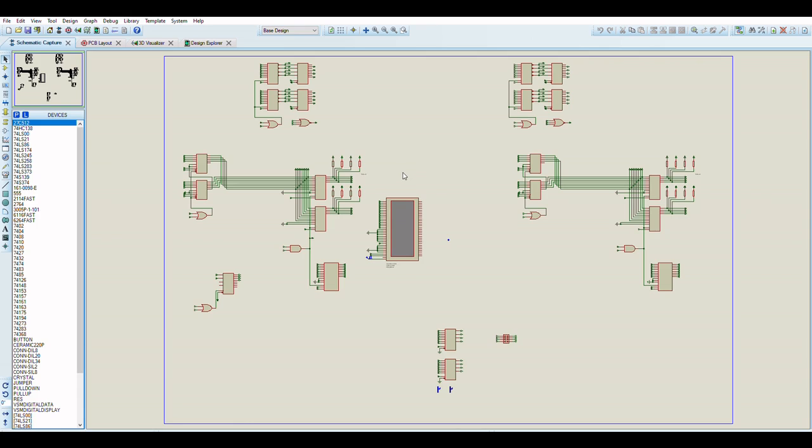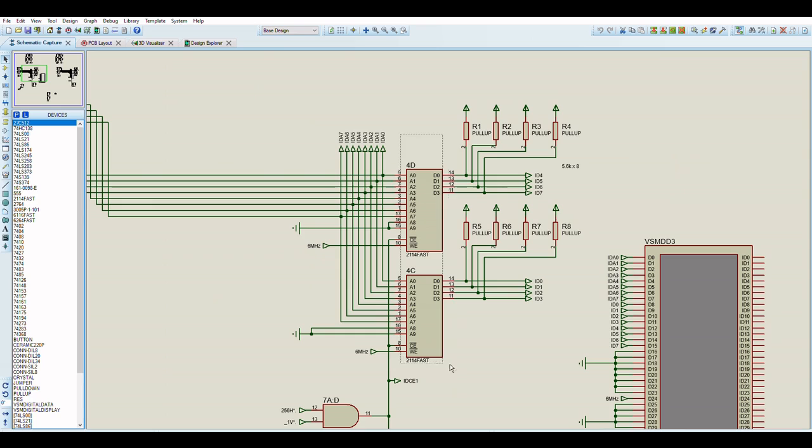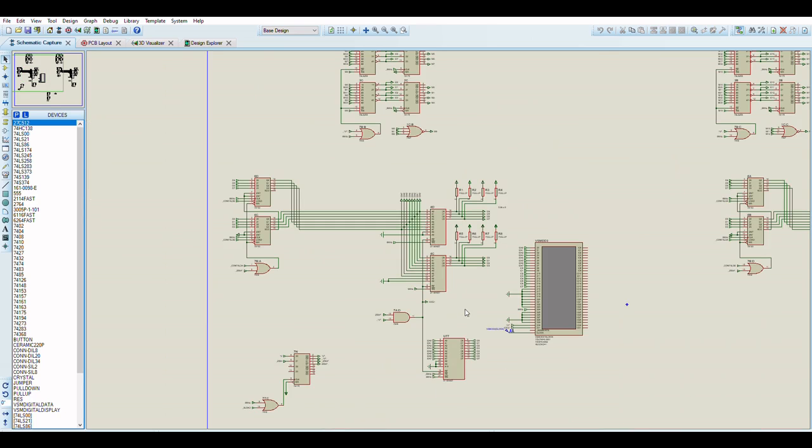So this logic, first of all, I have a little digital data component here, which actually lets me record what goes in on 4C and 4D. 4C and 4D were the original scanline RAMs. I think I actually replaced it eventually with one RAM rather than having two RAMs.